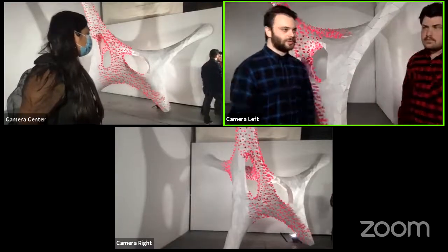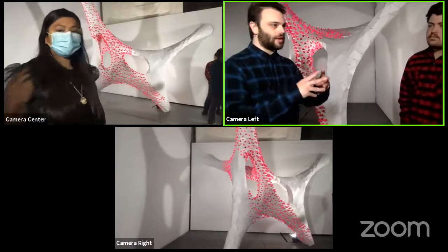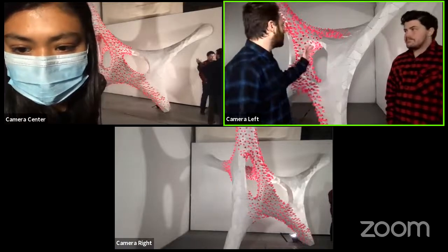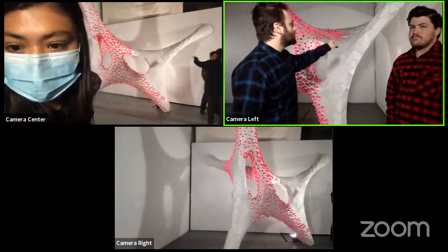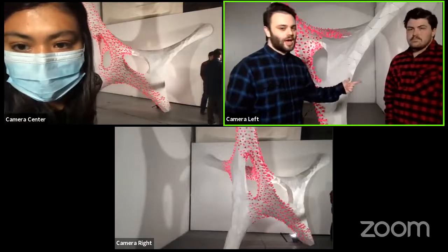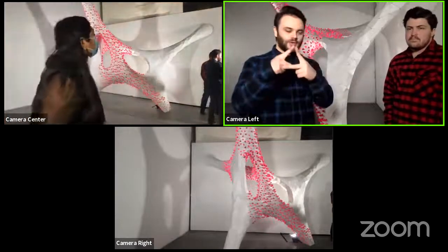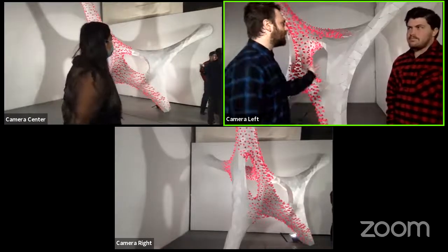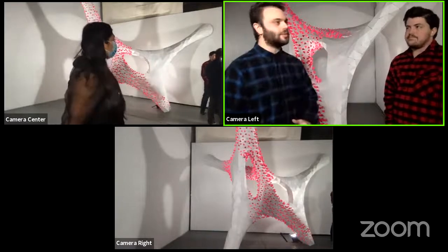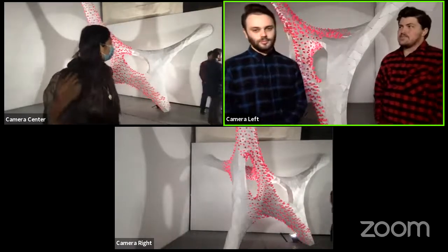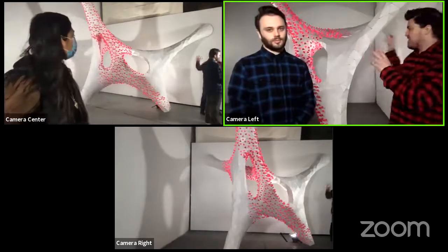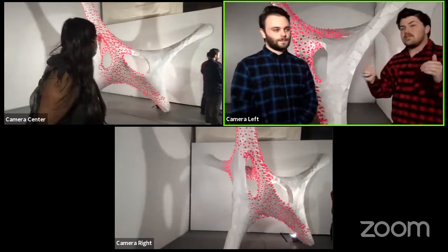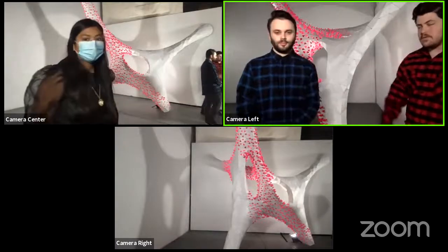And speaking of those material estimates, back in that form finding video, when it became triangulated, we ran some multi-objective optimization processes on it with particle swarm optimization software to minimize the number of strips and maximize the average length of each strip so that we didn't have any singular face strips. At least they would be 2 faces, and they would be the least amount of total strips, because that cuts down on assembly time and material usage. So in layman's terms, we are trying to make the most amount of faces per strip, so in total we had to laser cut fewer parts. Exactly. And there's less labor involved.